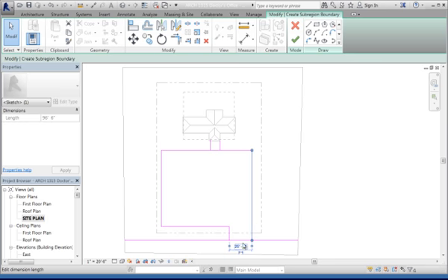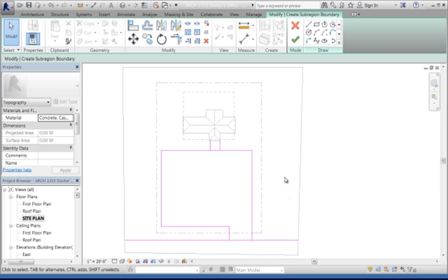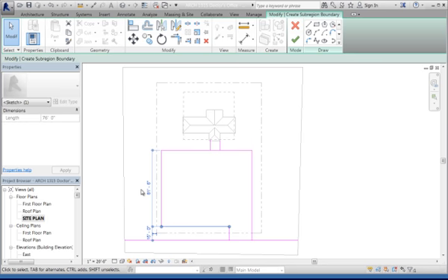And this is where you can look in the graphic standards, which is up here by my desk, for driveway widths, parking stalls, stuff like that. You need to look that kind of information up to make sure you have room for a car going in and a car going out. So I've made that 25 feet. Let me just see how wide this is. You want to look at parking lot layouts and see how wide this needs to be, because on this piece of paper, you probably should do these calculations first.